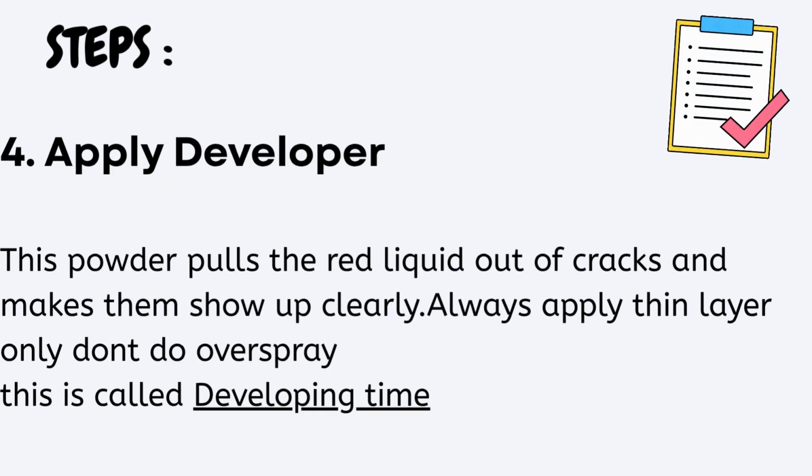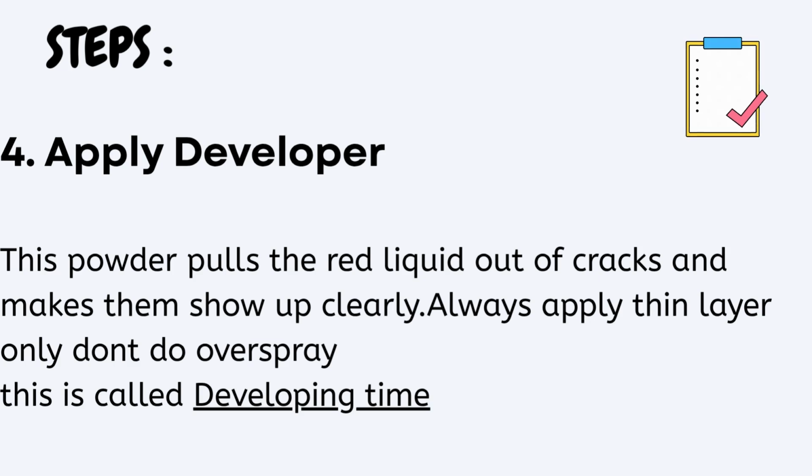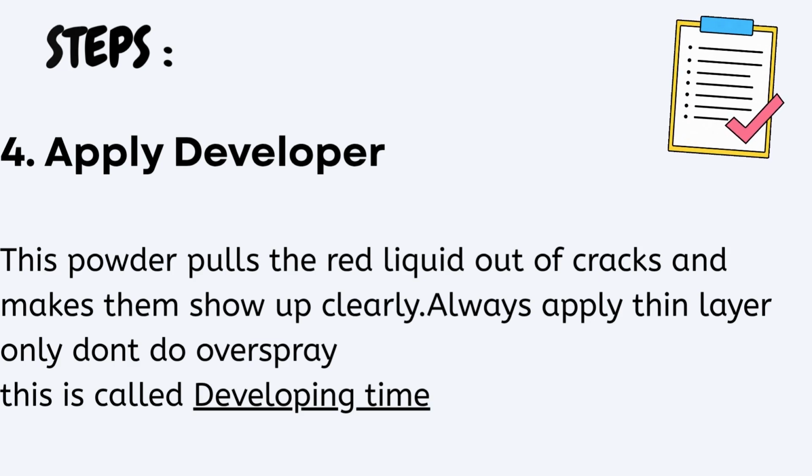4. Spray white powder, the developer. This powder pulls the red liquid out of cracks and makes them show up clearly. This is called developing time.